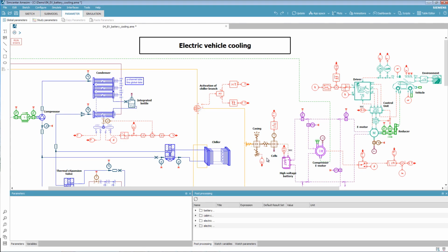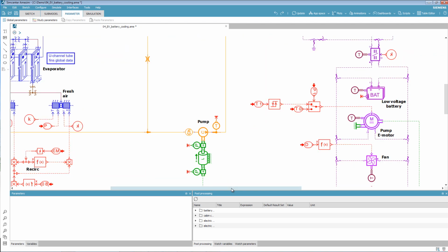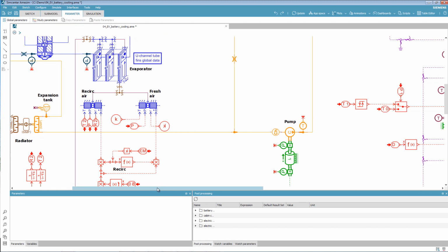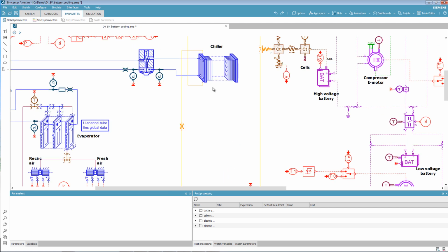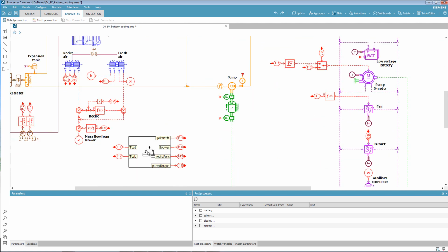The battery thermal model is represented with two separate masses, one for the cells and another one for the casing. A water cooling heat exchanger is directly connected to the casing to cool it. The two cooling power sources in this exchanger are a radiator, which cools down the coolant with an ambient temperature airflow, and a chiller, connected to the air conditioning loop to get more cooling power. The cooling strategy is defined through a state chart, depending on battery and cabin temperatures.